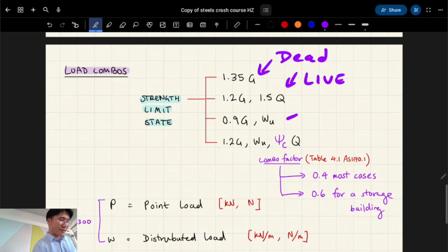And you also see other ones. W is wind load. Things like this, right? More commonly just dead and live load. But the idea is that dead loads are things which aren't going to be moved for like 100 years, essentially. They're called permanent loads. And live loads are things which would move over the course of a day, a year, things like that. So the shorter term loading.